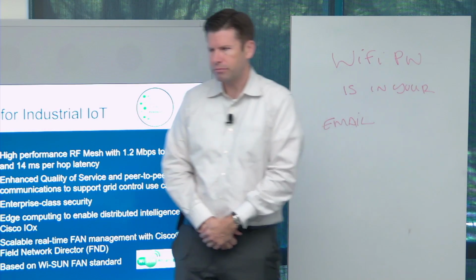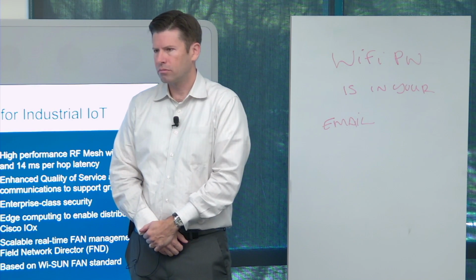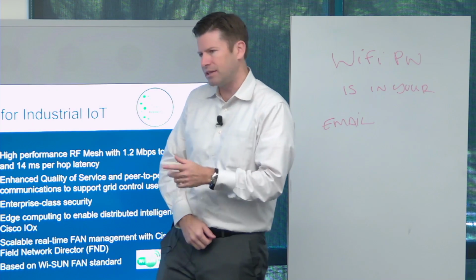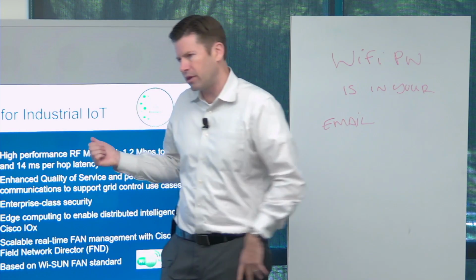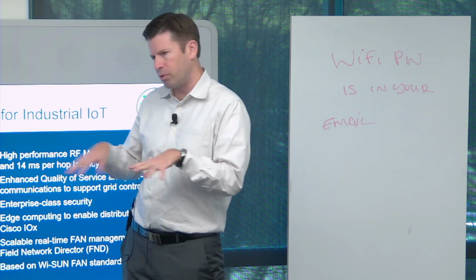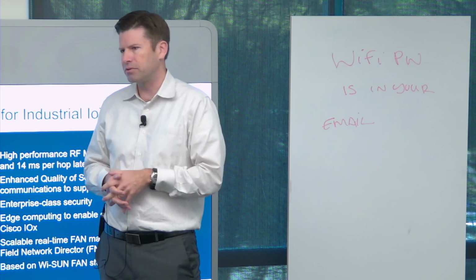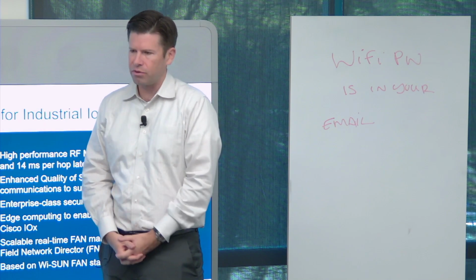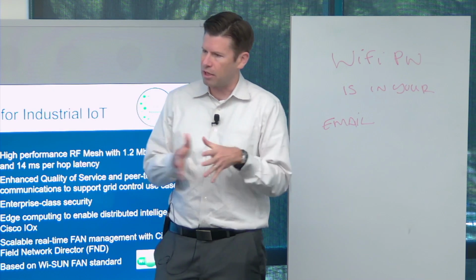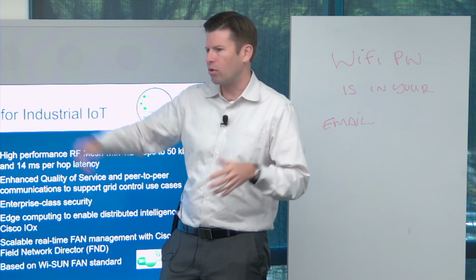With 800 and 900 megahertz, you can have pretty good distance between mesh nodes, and you don't have as much interference. This is a mesh network, so every sensor is a repeater in the network, and the link distance will vary dramatically based on data rate as well as the physical topology. On average, the networks we've been deploying today for smart metering run at roughly 150 kilobits per second, and the average distance is about a mile between hops. But in urban environments, that's going to get much shorter, and in rural environments, it'll grow to more than a mile.